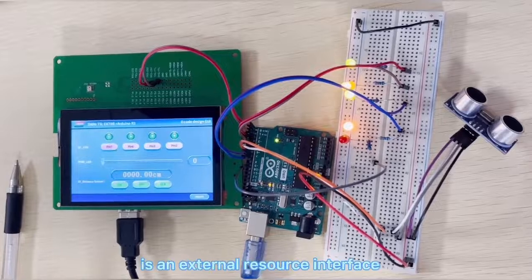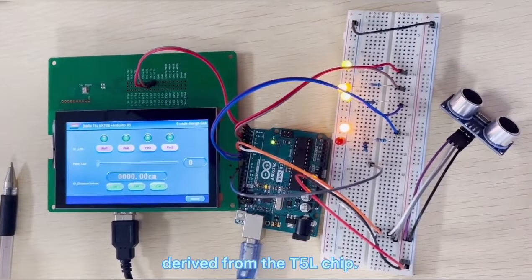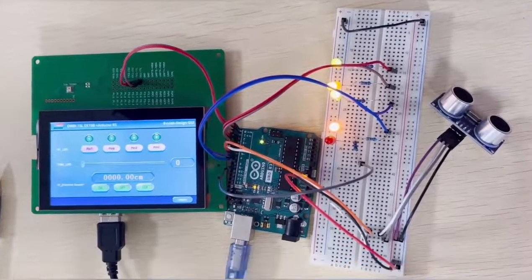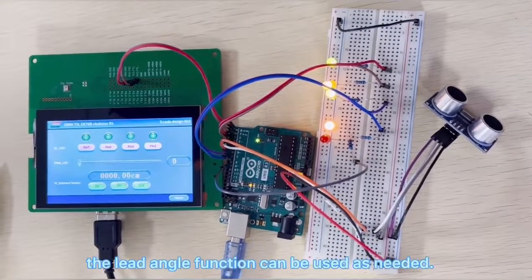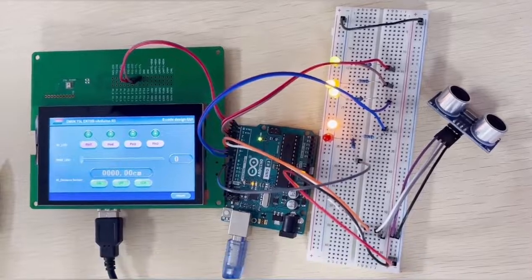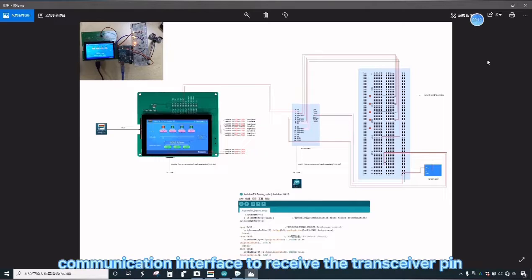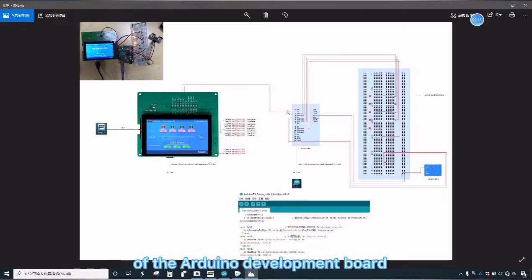The development board is an external resource interface derived from the T5L chip. There is a lead angle definition on the side of the through tube pad. The lead angle function can be used as needed. Here is serial port 2, connected to the sending and receiving pins of the development board. The pins are at TTL level. It is connected from this communication interface to the transceiver pins of the Arduino development board. Here, the transceiver pins are cross-connected: T to R and R to T.